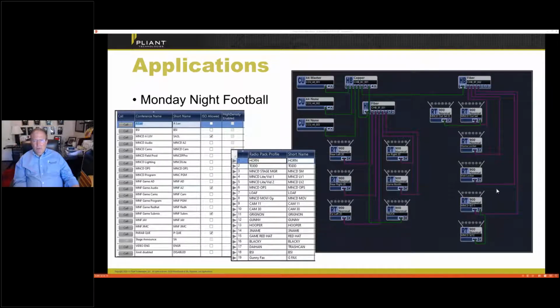They'll take 4 of those transceivers. Those will be in the stadium proper. And if you take a look on the right side, you will notice the top 2 have a green line as well as the purple line. So what they do is they run fiber to the first one, they're running power to all of these, and then they daisy chain the second one. And you'll see that at the bottom. So one is on the home side, one is the away side. They put 4 transceivers in the arena. It covers everything that they need.